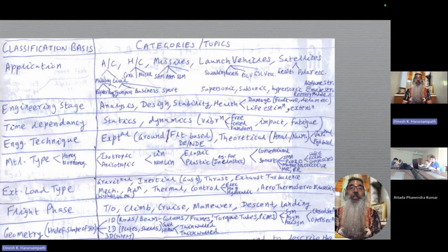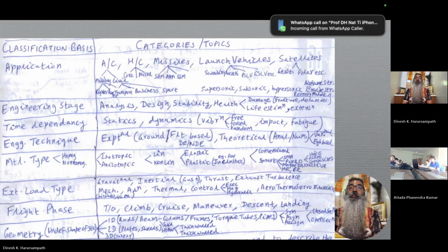And this observation will be of very critical nature for your second assignment, where we talked about, for each one of those classes of aircraft, if you're trying to find which materials are used and which part of the aircraft they go into, you will see this difference. For the nose of the fuselage, the leading edge of the wings and the stabilizers, and some parts of the engine as well, you will see that there is going to be a difference in terms of the material used, because the materials used there have superior impact responses. In other words, they are able to absorb more energy.